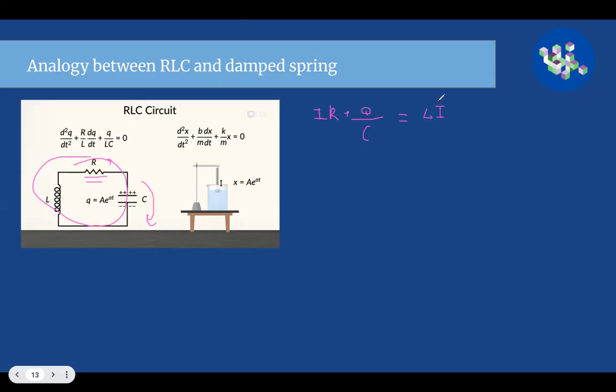Now, we can also say that the capacitor originally had charge, and then we're losing energy in the circuit, so the capacitor is going to be discharging. So the charge on the capacitor is decreasing, so Q dot is less than zero, but we know that the current is positive. So we'll say Q dot equals the negative current.